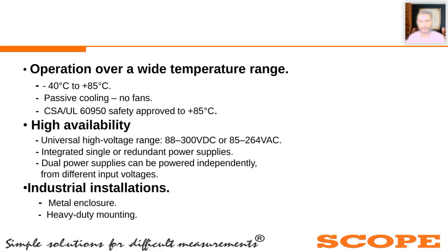Normally, whenever you are selecting switches, there is something you need to specify. You need to specify whether you require a dual redundant power supply switch or a single power supply switch. If you opt for a redundant power supply, then in case of power supply failure, your switch will still be in operation because of redundancy. And there are various ranges of power supply based on the availability at your substation or plant level.